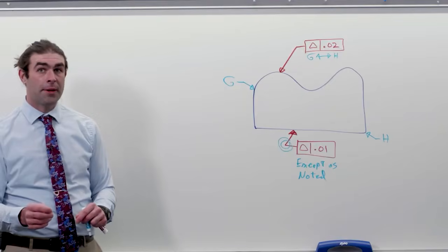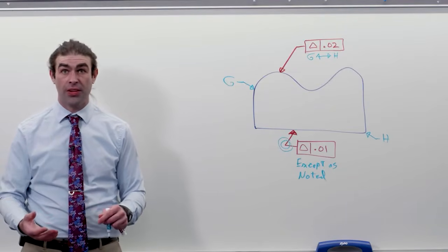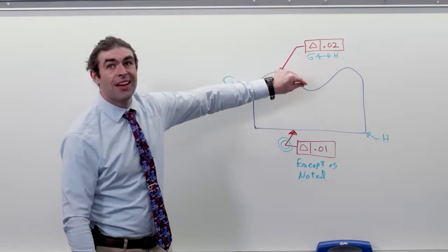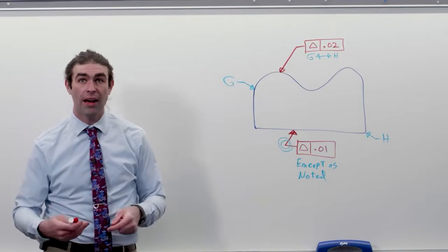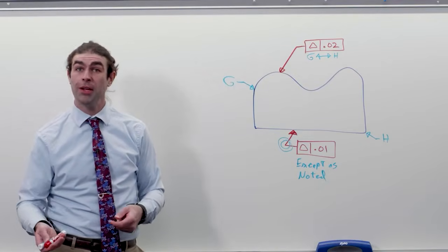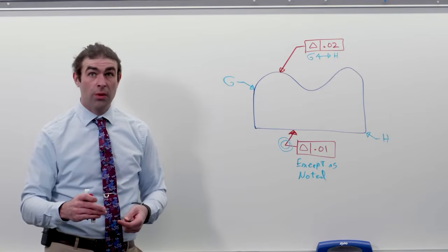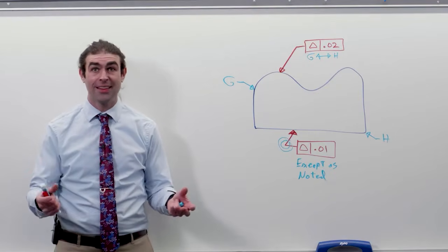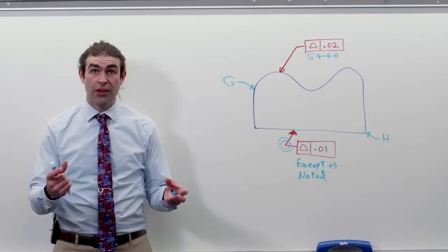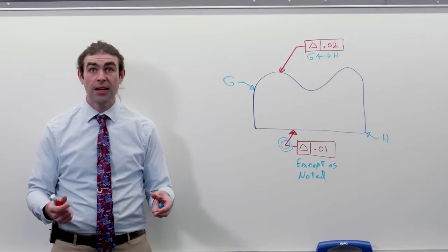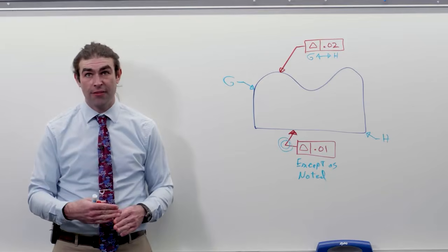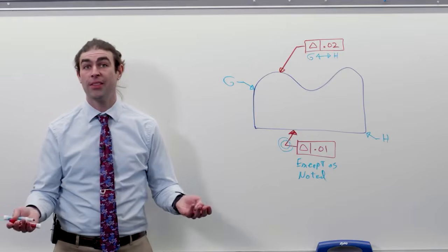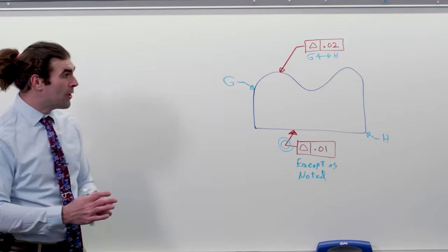So the default requirement is a bilateral equal tolerance zone. Like I mentioned before, with this 20 thousandths, you got 10 thousandths on one side and 10 thousandths on the other of the true profile as defined by the basic dimensions. That's not always what the designer wants. So often you would have two mating parts where the basic size is 1 inch. So instead of changing the nominals to make them fit, you could just say, okay, I'm cool with the line-to-line fit. I'll make one unilateral in one direction, the other unilateral in the other, and they're going to fit up no problem. The way that we do that